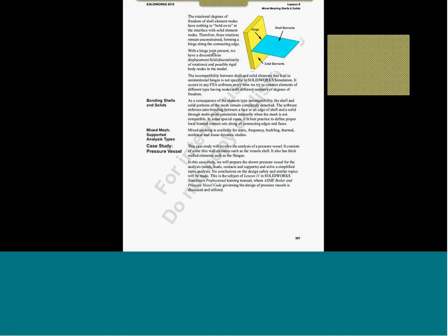By saying that, the way it works, it will not transfer the rotational degrees of freedom, the displacements coming or the movements in the rotational direction, to the solid mesh. So we need to handle it appropriately for that.